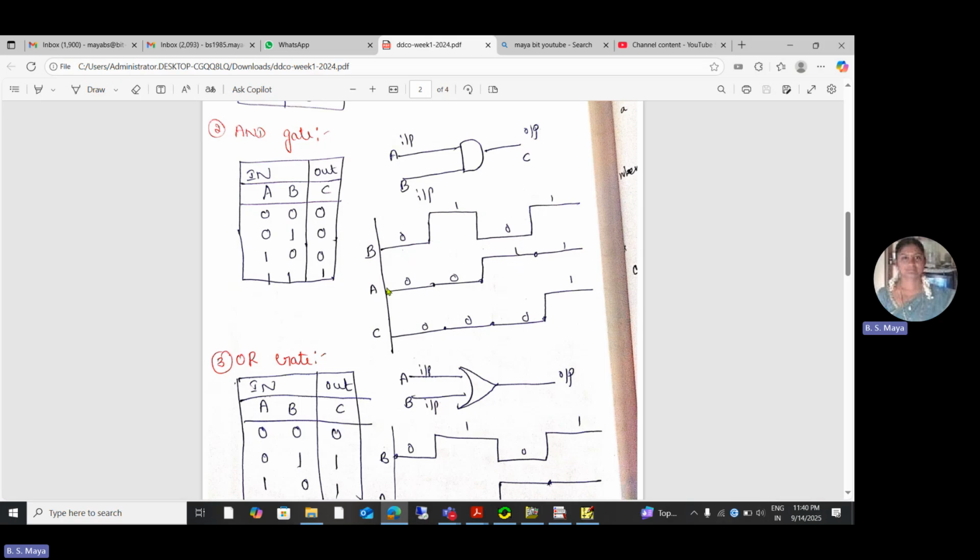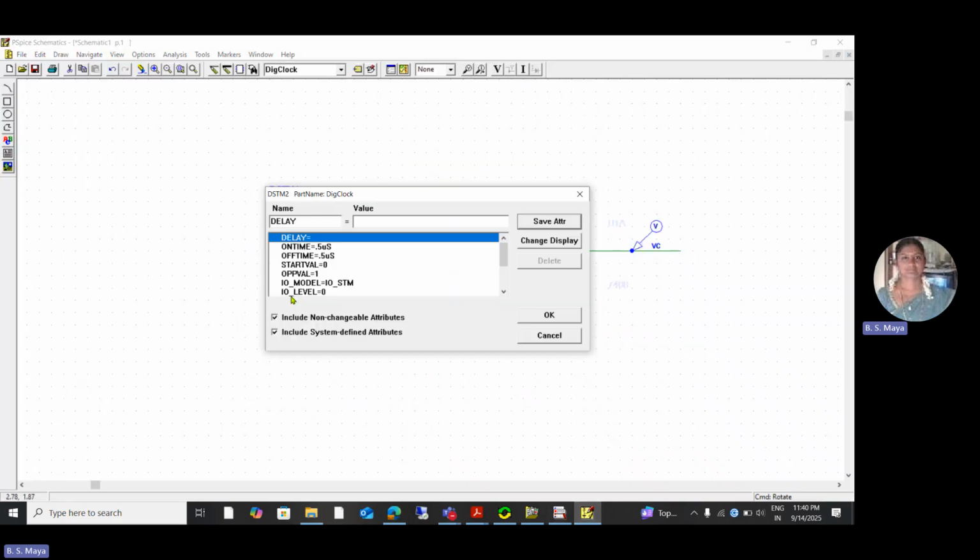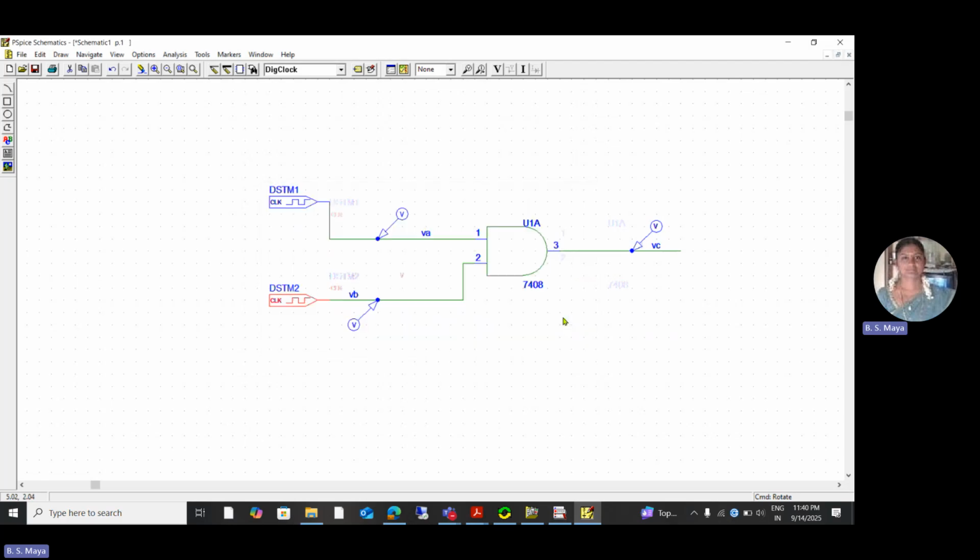If the next input is also given 2 milliseconds on and off, you won't get the difference in the 0, 0, 0, 1 combination. For that, you need to change the combination. Next, I give 1 millisecond on, because I have to generate 4 possible combinations, so I change that attribute value for the second one.